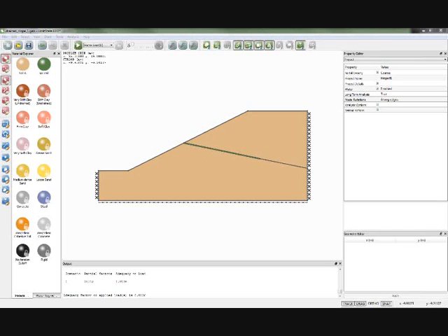Essentially, the software, because it's based on the theorems of plasticity, is designed to analyze the ultimate limit state. Its power is its ability to go straight to the collapse mode using optimization, whereas in finite elements, you would have to increment up to that stage. Because it does that, it's not able to actually model deformations and therefore deal with progressive deformation. We are looking at large strain or large deformation type mechanism problems and being able to model those, but that's some way off in those terms.